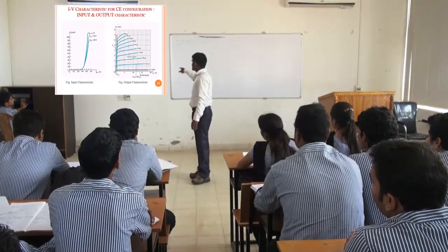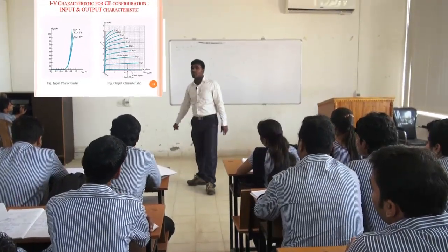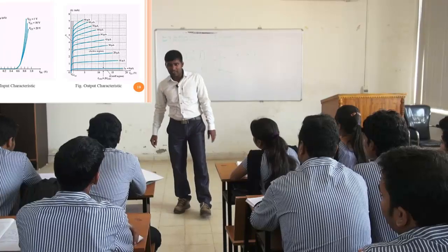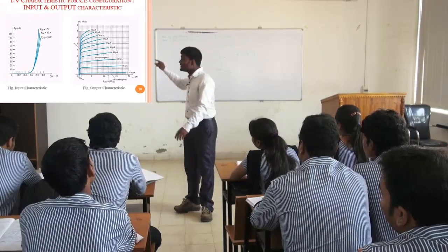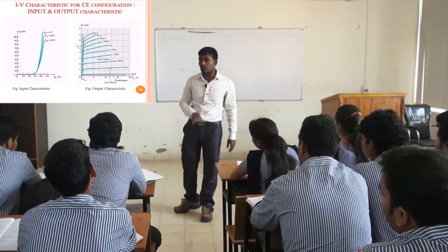In this output characteristic, you have to keep IB constant. You have to fix the IB value. For input, you have to fix the VCE value.